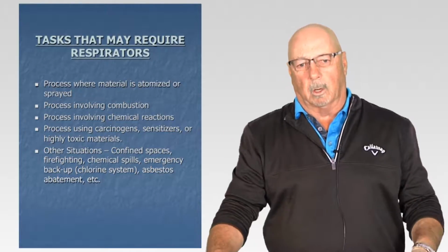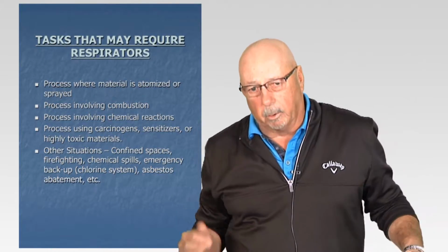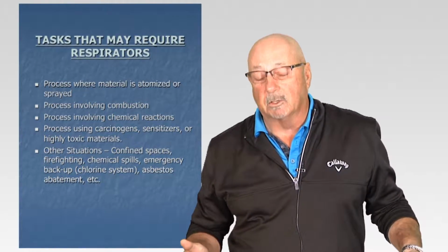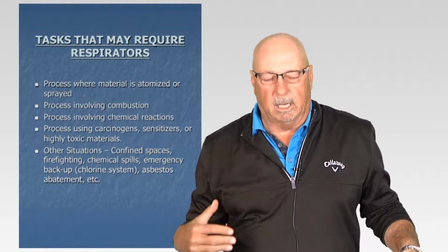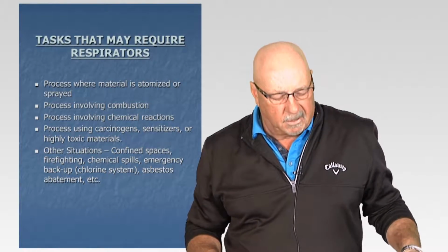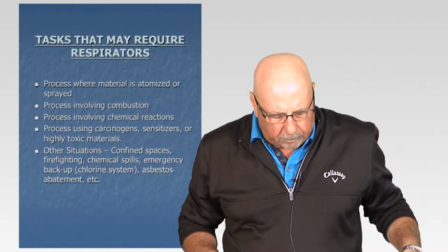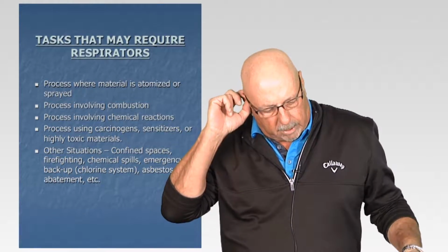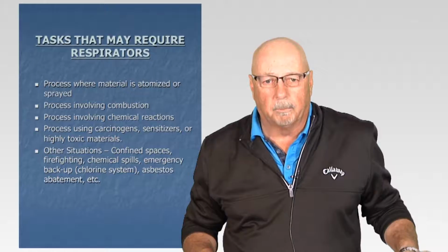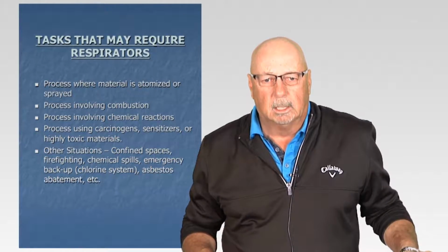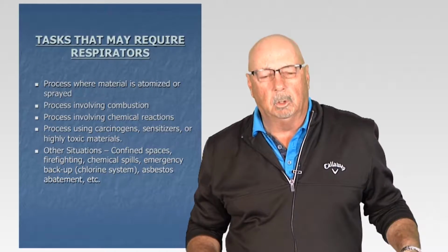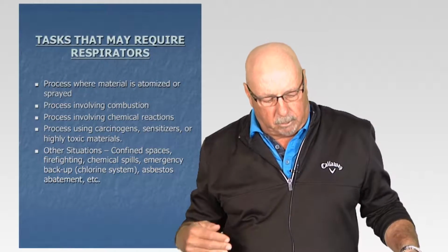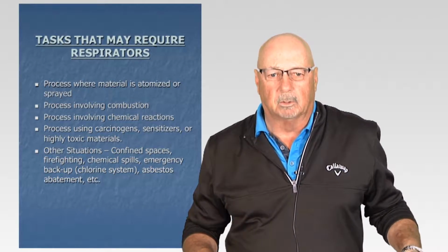Some of the other situations where we can get into respirator use would be if we're entering a confined space and we have the potential of not having a sufficient amount of oxygen present, or where we might have dangerous atmospheres that are created by materials that are present inside of that atmosphere, which would require our employees who are going to enter those spaces to wear appropriate respiratory protection. A real obvious use of respirators is if you're in the emergency response or firefighting industries, if you're in a situation where you're responding to chemical spills.